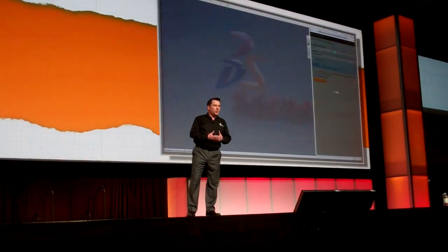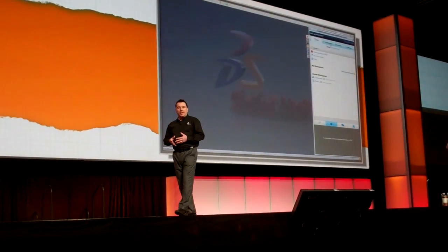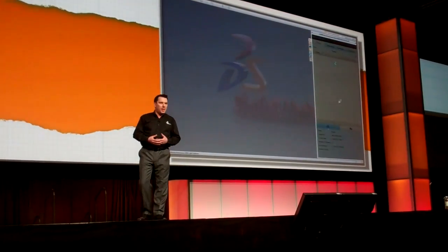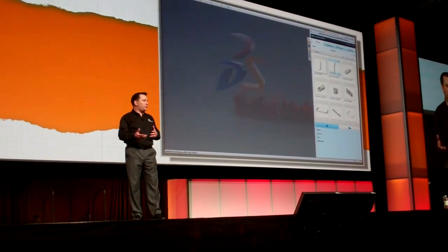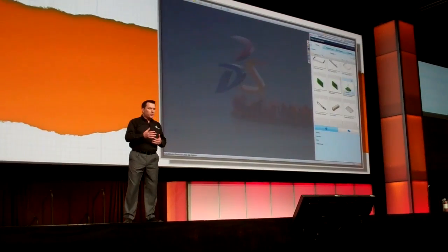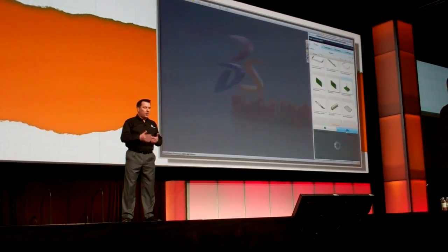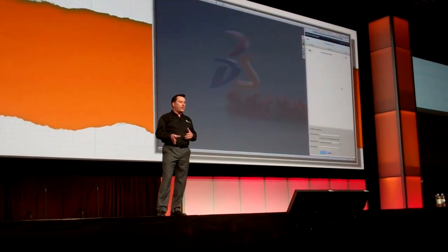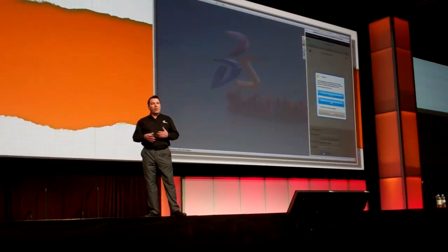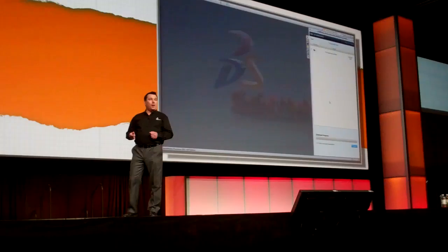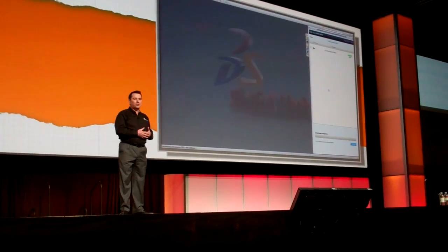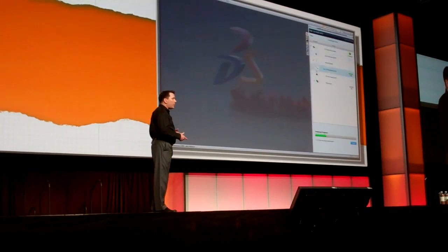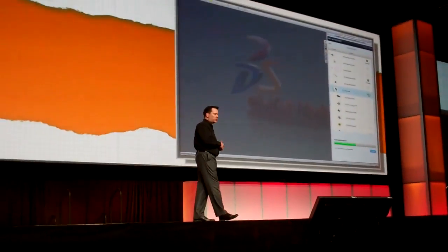Now once we've posted that comment, we'll move on to the second user. User 2 then logs on to SOLIDWORKS Fuze and sees that he has some notifications. This keeps track of the history of what's gone in this design, files that have been added, deleted, up-revisioned, and so on. So we'll see the PCB assembly and we'll check out the comments. We'll go ahead and download it directly from the add-in straight into SOLIDWORKS. Now it already knows what files you have on your hard disk, so it only downloads the files that you need, again, to make it more efficient. When it's finished downloading, it's going to go ahead and open it in SOLIDWORKS.